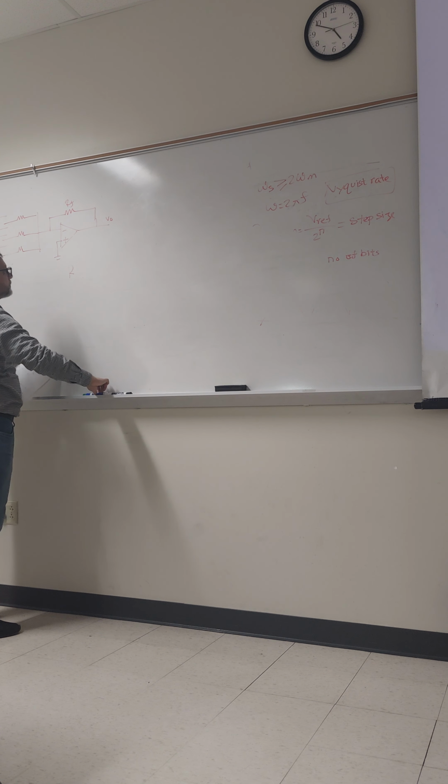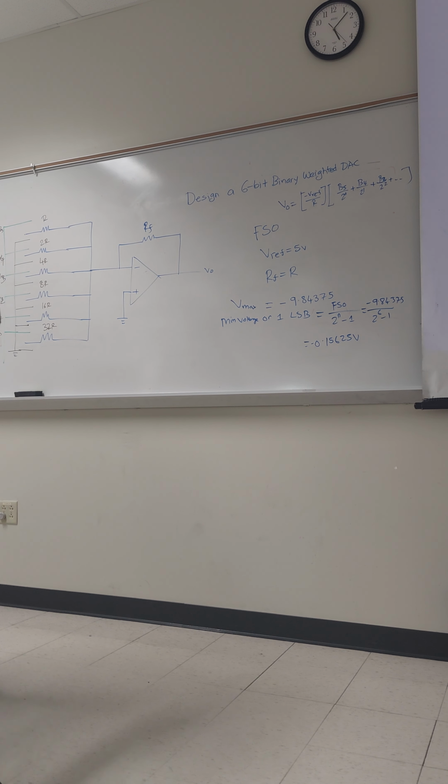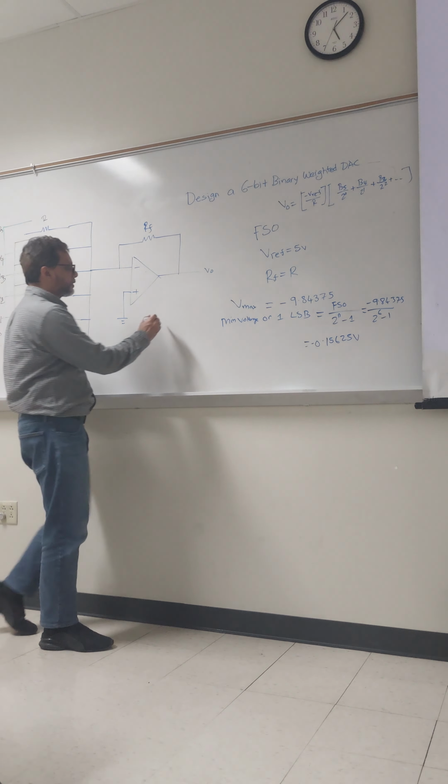The minimum step size, the proper term is the step size, or the resolution, or 1 LSB. Sometimes they say the minimum input voltage is some voltage that is not zero. That means they are actually referring to the 1 LSB. So we can see that if we increase the number of bits, the value of resistance increases in the power of 2, right? 2 to the power n.